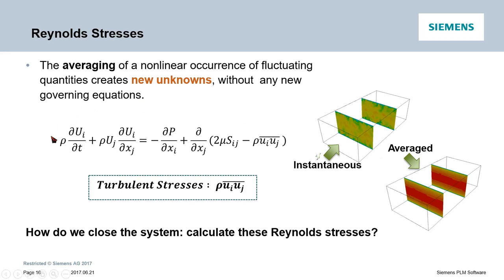So if I look at my equation again, the first term in this bracket is the viscous stress term. So the second term is naturally interpreted as turbulent stresses, or more formally Reynolds stresses. And now this is essentially the task of different turbulence models, at least RANS models, to calculate these turbulent stresses, which can now be fed back into this RANS equation to close the system. But to develop those models, we need to first understand what these stresses are and what drives them, so that these drivers are major elements of any model we come up with.